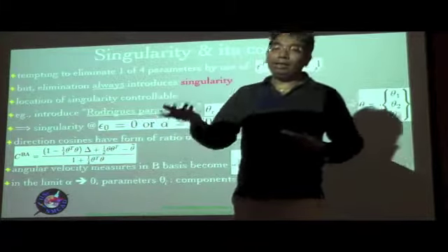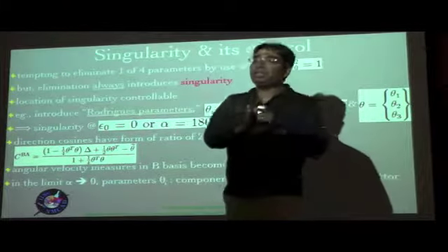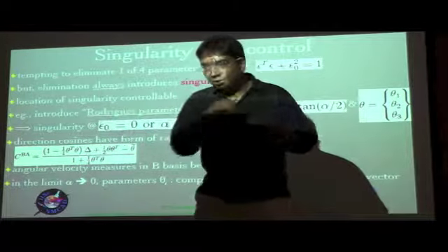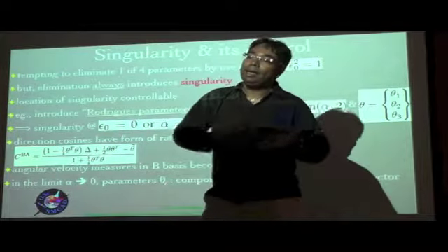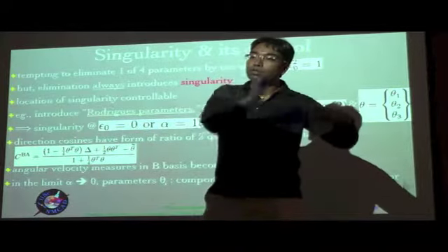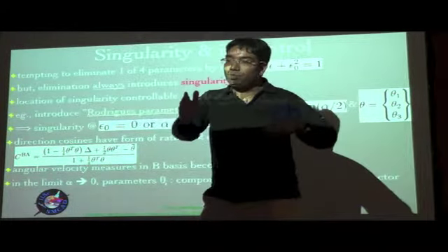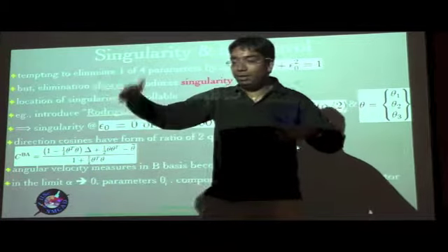This again comes from the fact that, for example, we have an intermediate reference frame. We already talked about that. So we want to rotate from, let's say, A to T and T to B. Then the total rotation C of B in A becomes C of B in T multiplied by C of T in A, right?